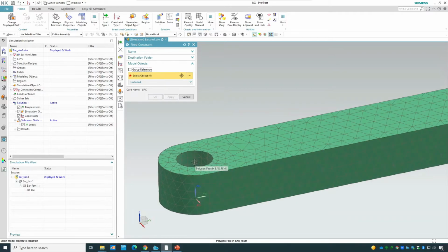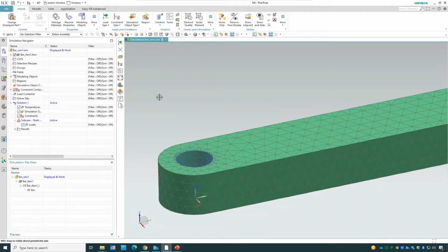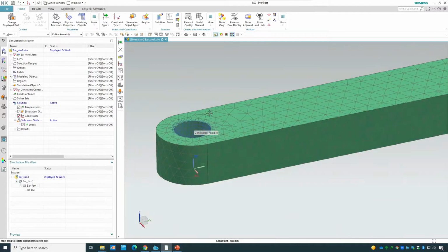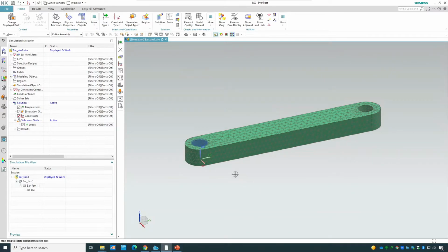single element of that hole. So none of those elements would then change. I'm gonna make sure the inner part of these holes is picked up. I'm gonna click on OK, and you can see the fixture representation the software shows to make sure this part is fixed. Now I'm gonna insert the force on that area.